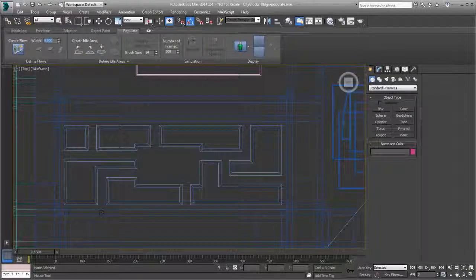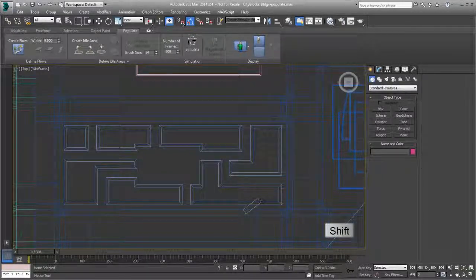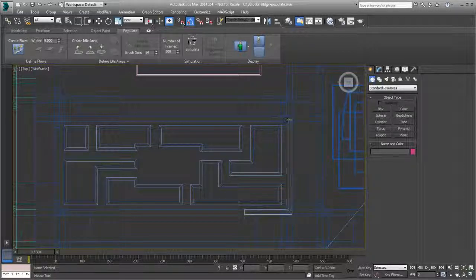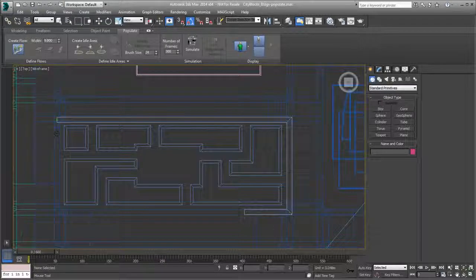To start the flow, pick a point on the sidewalk away from the corners and away from the pathway intersections. This will prevent any problems when you start inserting flow direction changes later on. Hold Shift down to work in ortho mode and go around the building lot without worrying about the chamfered corners. Right-click to end the flow.